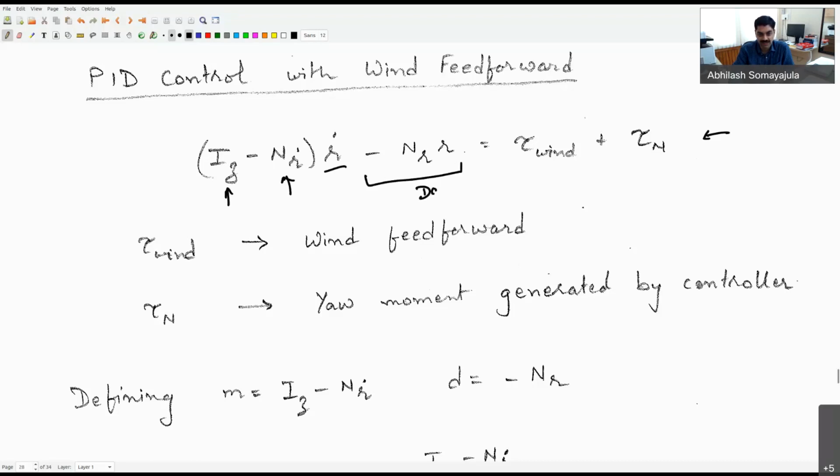So this is the damping term, and that is equal to the external forcing. The external forcing can be coming due to two aspects. One could be due to the wind, and the other is due to the effect of your controllers. The moment I apply a rudder, there will be some thrust which will be generated. So this is a very simplistic model, but gets the job done for most of the cases when we are looking at a heading autopilot being operated in the open ocean.